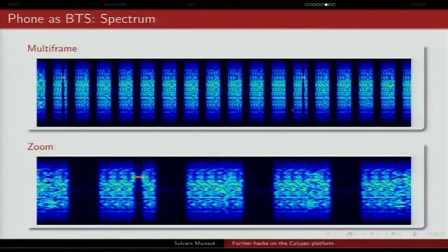So if you look at the spectrum of what it looks like, for those of you that are not familiar with a waterfall diagram, in this direction you have time, and this is frequency, and this is just the FFT of the signal essentially. And you can see that it's discontinuous because of the half duplex operation. So here I'm transmitting something, then during this time slot, I need some time to retune the PLL. It's just not instantaneous. It doesn't take a full time slot, but once I've lost the start, I can't use it anyway.